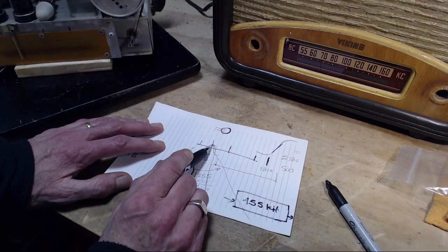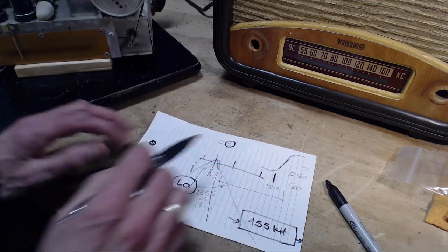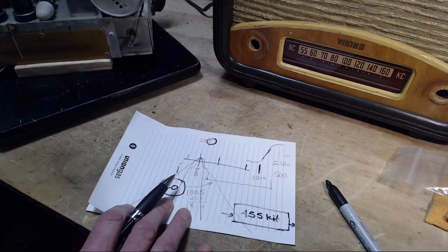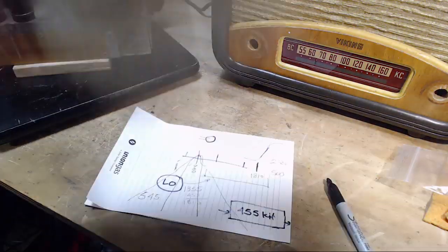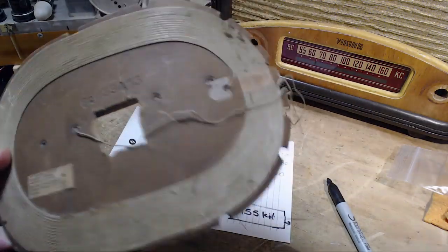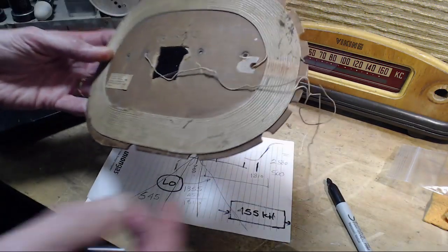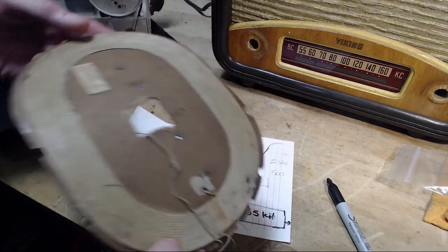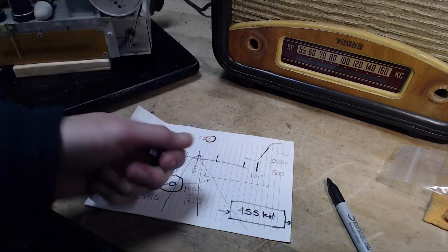Now some radios are really poor on this, really, really poor. So let's say you get a radio with a back missing, and the back of the radio had that loop on it. So that's not just a wild loop of wire. This is a carefully constructed antenna with a certain electrical impedance. And this coil would be matching up almost certainly with the tuning capacitor.